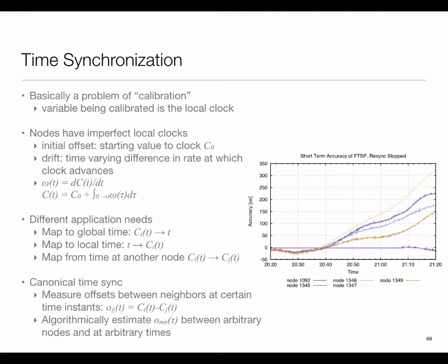And so I know right now it's 12:30 p.m. and I say, okay, I want to fire the actuator at 1 p.m. So what would be the counter value at 1 p.m., and then I set the thing to that. The problem though is that between now and 1 p.m. I really have to make some estimate of how my clock will drift. Okay, and I have to be willing to correct for it.